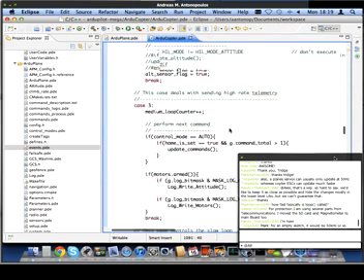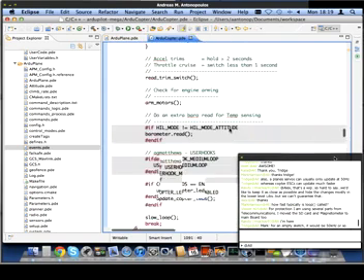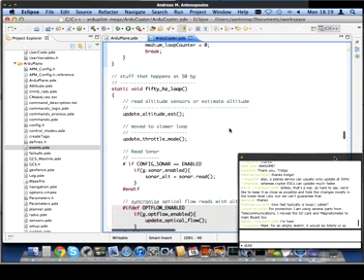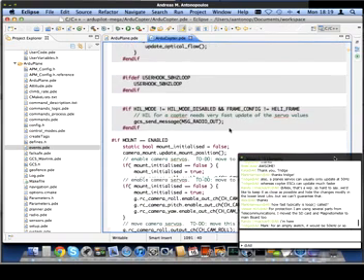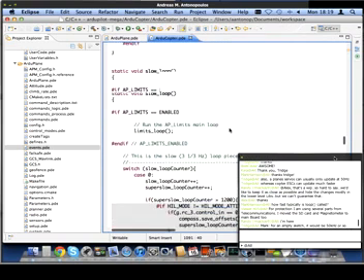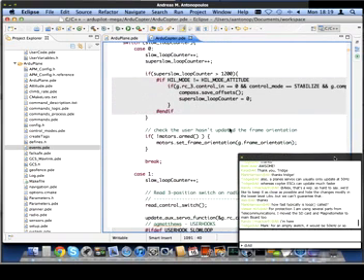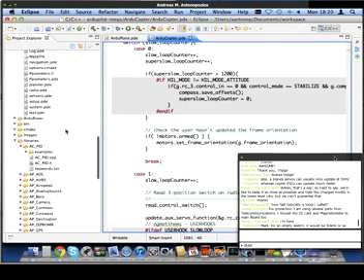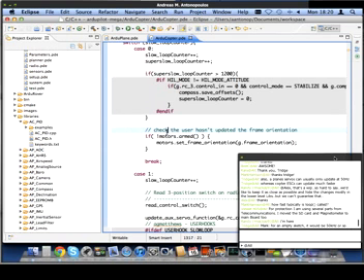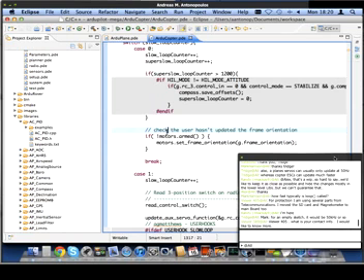So I'll continue in the meantime. As you can see, the loop strategy is very, very similar to ArduPlane. So for example, when we're calling medium loop in at 50 hertz, we then split it into 5 10 hertz sections to run 5 different sets of capabilities at 10 hertz. And many of the other parts of the code are very, very similar to the way that ArduPlane works.